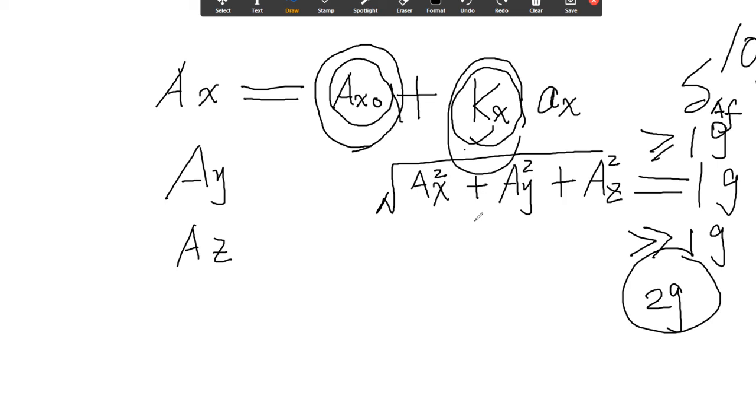Another method is that you detect whether it is walking or running or sitting down or resting. You need to classify this because this is very important for motion tracking. Maybe you only detect two, for example, walking and running. Can you tell the difference? One method is just to use a threshold. After you measure the rate of your exercise, you can tell that running is faster than walking, and then you find the threshold.